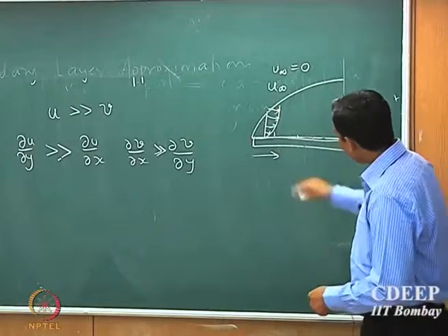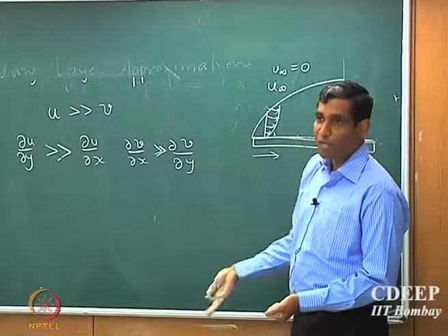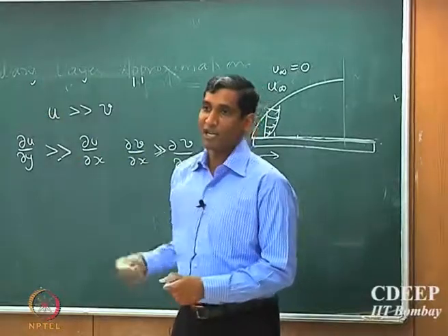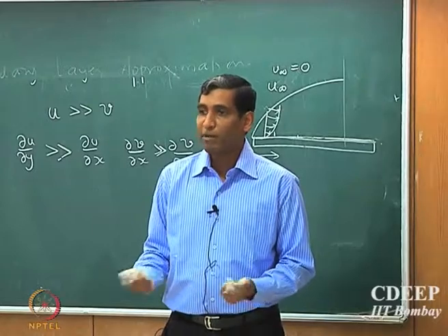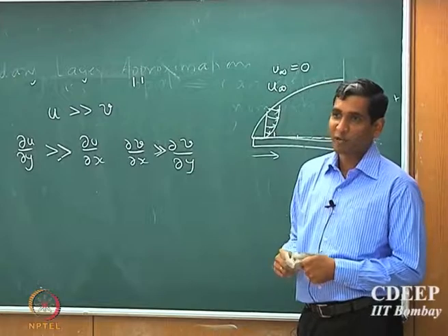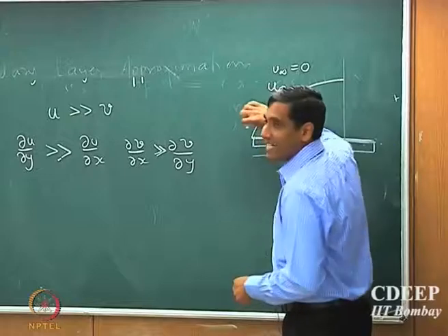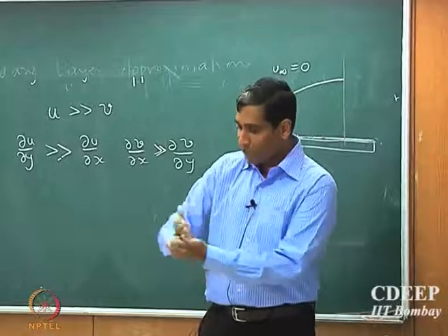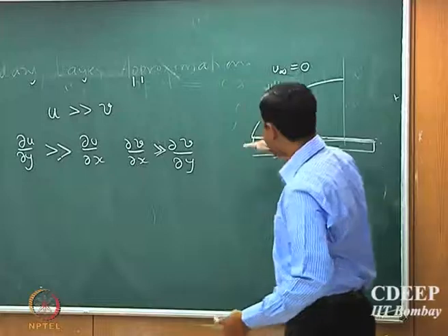But then because some of the fluid particle velocity has now changed and some of them have actually come to 0, right? The x component velocity has come to 0. The continuity equation will force that there has to be a dv by dy, otherwise the continuity equation is not satisfied, and because it is an incompressible fluid, you must have a y component velocity in order to satisfy the continuity equation. Now the slowing down or the gradients in the x direction that you will get is simply because of the shear of the fluid offered on itself. So it does not feel the presence of the plate.